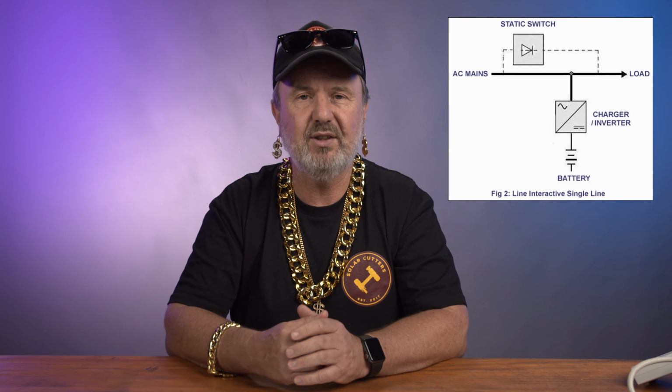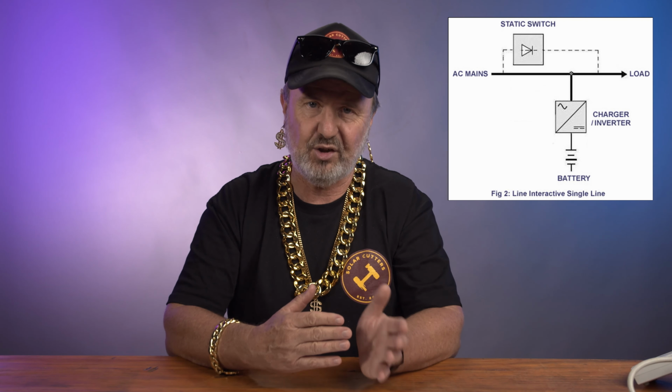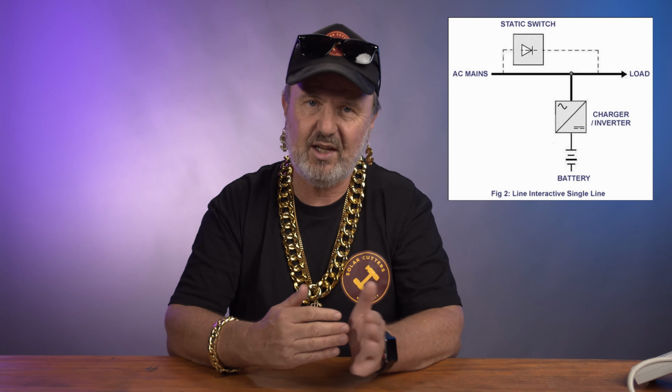What's an interactive inverter? It's one that can parallel its own inverter function with another source, such as a generator. That means it's running in synchronization with another source. It also means that energy can flow in multiple directions. It can flow towards the load, and it can flow towards the generator, especially under disconnection. Now, you don't want to send power back to a generator. It'll cause it to stall. But it is possible that when disconnecting a plug-in generator, there is a momentary reverse feed. And that reverse feed is basically a lethal voltage on some male pins of a socket outlet.